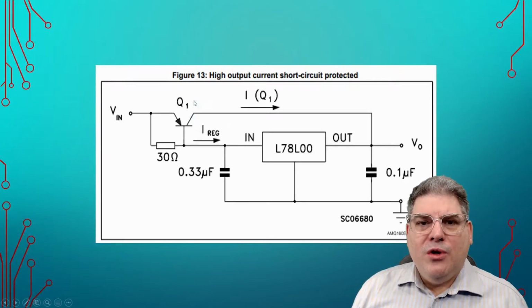You could get a huge TO-3 case on here, as opposed to the TO-220, which a 7800 series would be. And so the way this works is the bulk of the current passes through Q1 here, IQ1, and therefore never really heats this little part up. So does that mean that you get a freebie? No, the heat dissipation still needs to happen here.